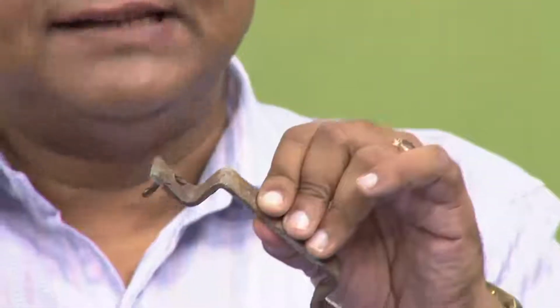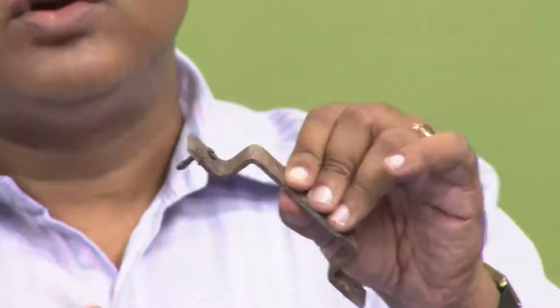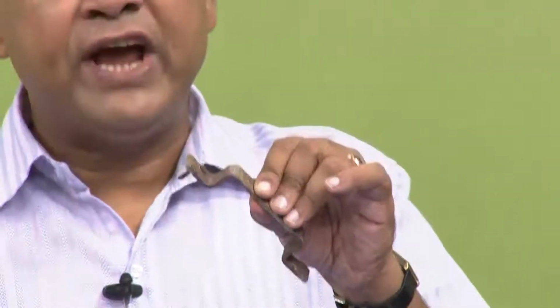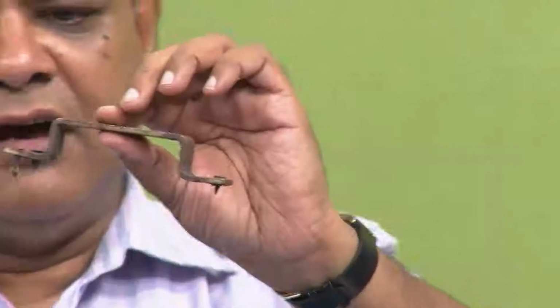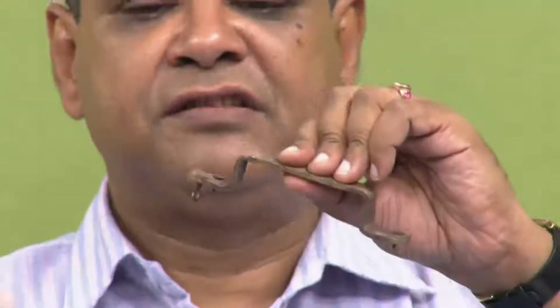would happen on this entire surface, but the bottom part where we do not have oxygen becomes my anode. Since iron dissolution, iron going into iron ions, is a strong anodic reaction, those reactions would happen here, and then those iron ions that are forming will combine with the OH minus that are forming, and they form red rust or hydroxide or hydrated oxides of iron. So, this again can be explained from the point of concentration difference of oxygen. This is a classic example, and you might see such things happen at several locations.